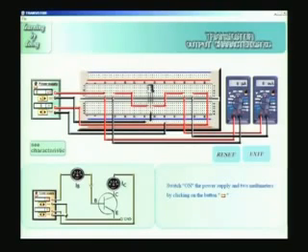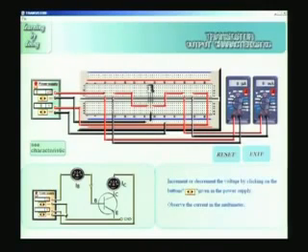Now let me switch on the power supply and the two current meters. Now I am ready. I will vary VBB, the base voltage, in steps of 100 millivolts, and as I vary this, you can see the base current keeps increasing. Now it is 4 microamperes. For 400 millivolt I increase to 500 millivolt, it goes to 5 microamperes. If I keep on doing that, for 1000 millivolt or 1 volt, it is about 10 microamperes in a typical case. This is reasonably a large voltage; even less than that you would get.